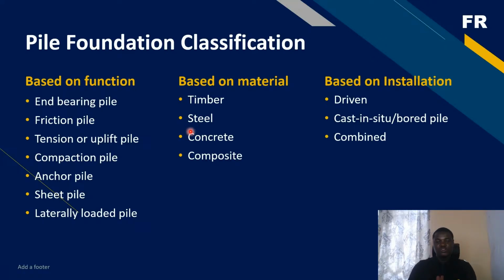it has to be precast, and then you drive it into the soil using pile hammers or any other driving equipment. It is usually driven vertically or at an inclination. So you can drive pile into the soil mechanically by using a hammer or other driving equipment. Using this method generates a lot of vibrations. So that is why the construction method is very important.